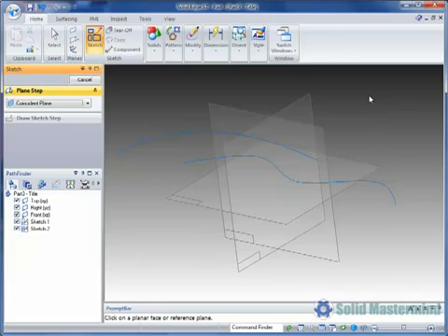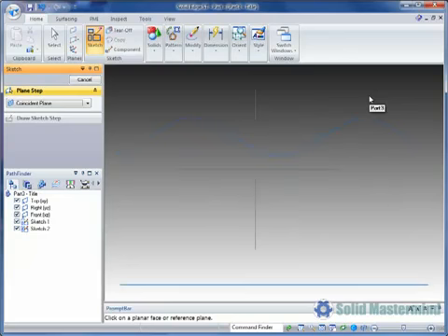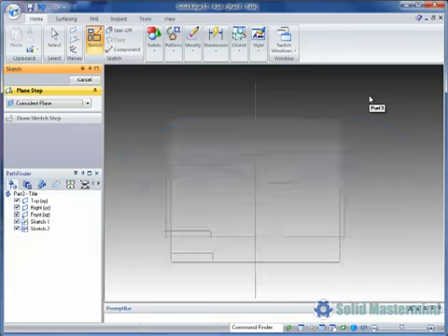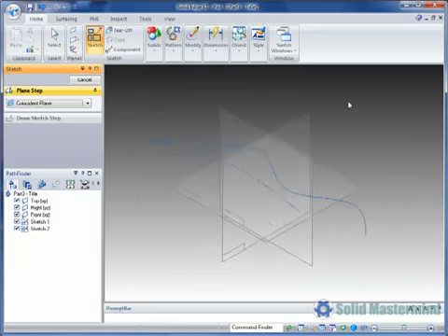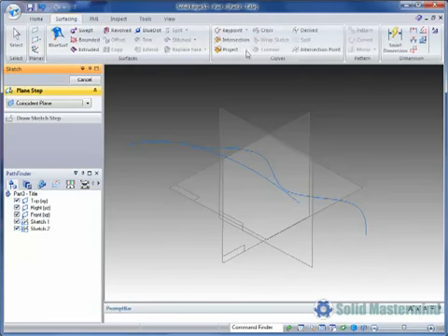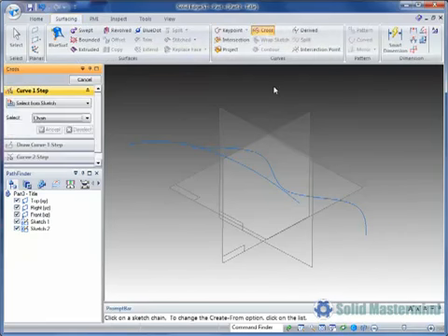These two sketches represent the shape of the curve we would like to create, the first one looking from the top and the second from the front. So we can now pick the cross curve command from the surfacing ribbon. The command bar will appear and step us through the creation of the curve.